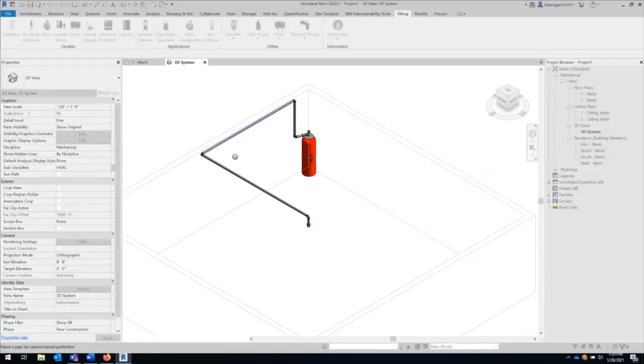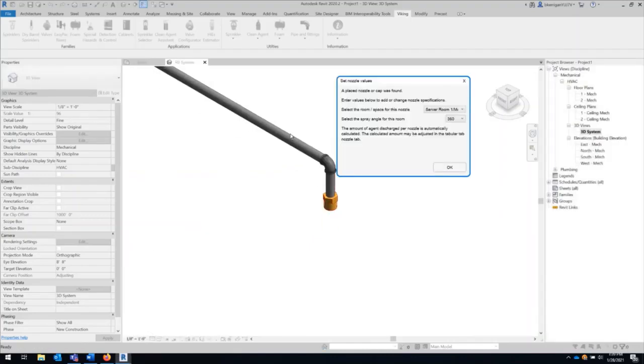And this is going to put me in a mode where I can go into Revit and choose any of the pipes that are present on that pipe network. And that's going to extract all those details out and get it ready for hydraulic calculation.